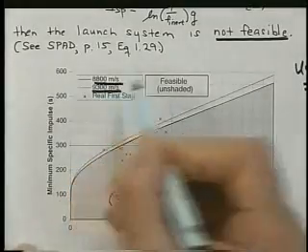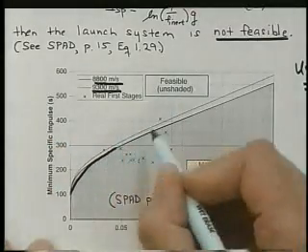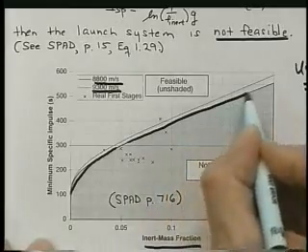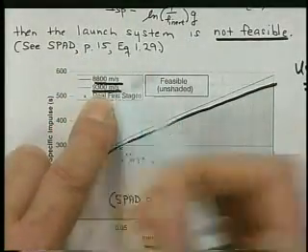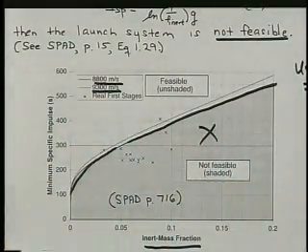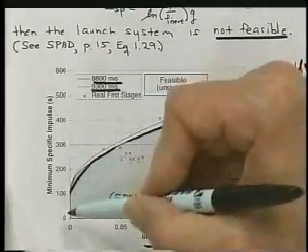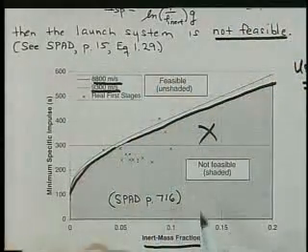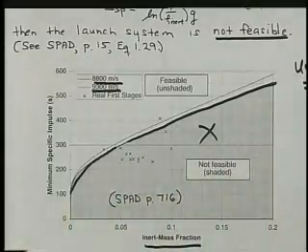If we go to a value of delta V a little lower, 8,800, then we get this curve here. That's the 8,800 curve. So depending on what value you want to use for delta V, these are just sort of two practical values. This is the area that you cannot use for a single stage into orbit. So here we have, again, the minimum specific impulse that you need in order to be right on the line of the feasible, infeasible cases.